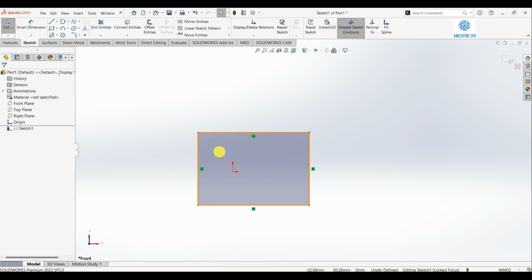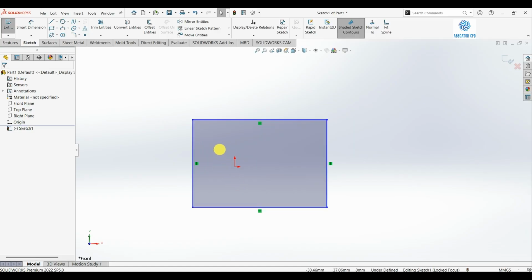It also improves the look of the part. We apply fillet and chamfer on sketch corners. On the corners of your sketch, anywhere two lines meet, you can apply them. Click the small arrow next to the icon. SolidWorks shows both tools. Let's start with fillet first, step by step.